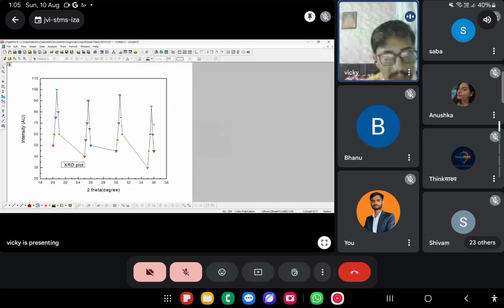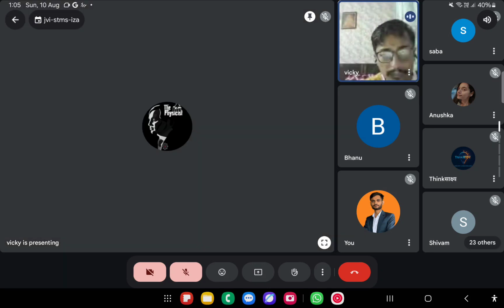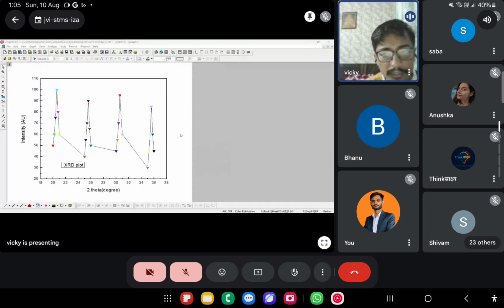You can go to the line part and select whatever you want, for example, spline, B spline, 2 point, 3 point, right? You can use solid, dash, dot options. You can change it. You can also change the width: 0.2, 1, 1.5, 2, and so on. And color, you can also change it accordingly. For example, if you want to use some other color, like blue, you can do it.